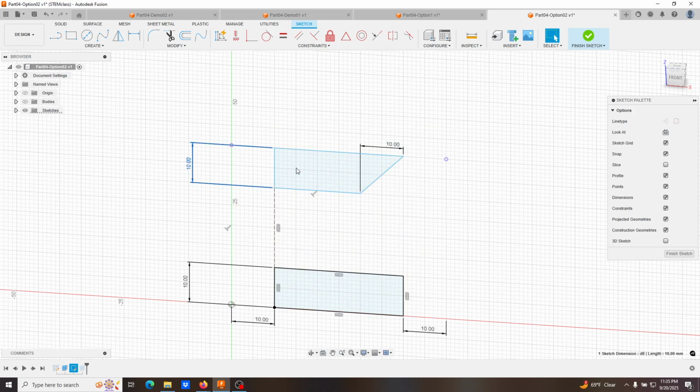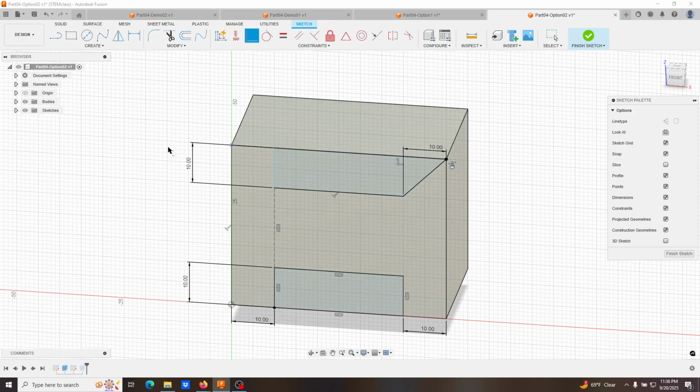bodies here and we can turn it off. So that way I can just see exactly where my sketch is. And actually this is a projection line that we have in there. So actually what I can do is I'll select this, I'll select this projected point, and can I make them coincident? Boom, and there we go. And then we have our bodies in here.